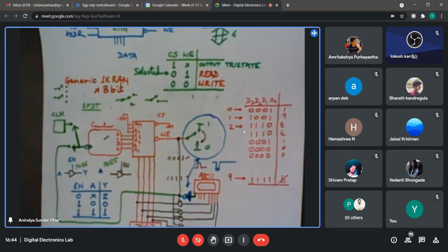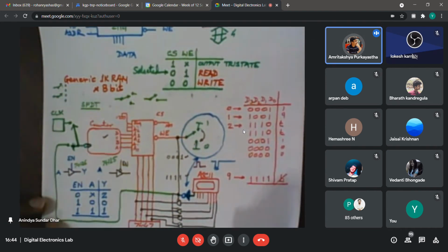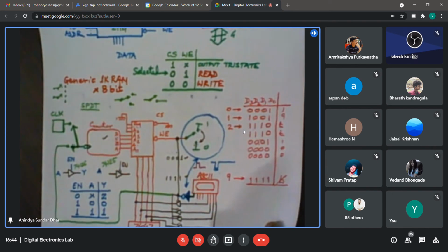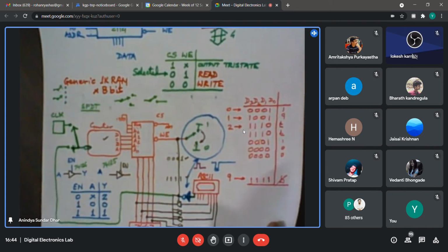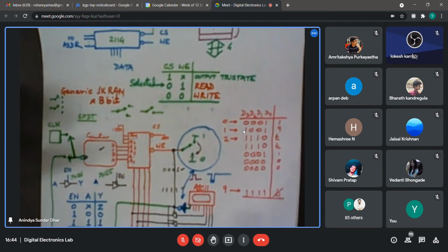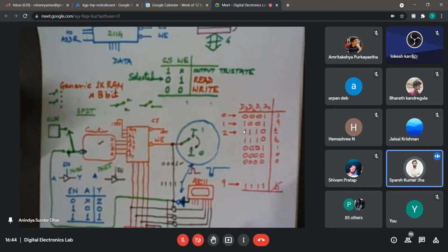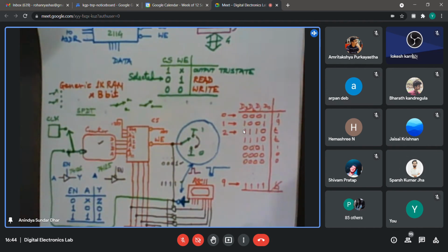For the multiplexers, do we need to use manual inputs like manual 0, 1? Right now yes, but you can actually decode some of the ASCII characters and use them properly, so that if you press a particular character, only then will it go into the display mode. If you put something else, it will come to the so-called programming mode, where you can change the data. So using the extra ASCII character, we can skip one of the multiplexers. Yes, so use it innovatively.